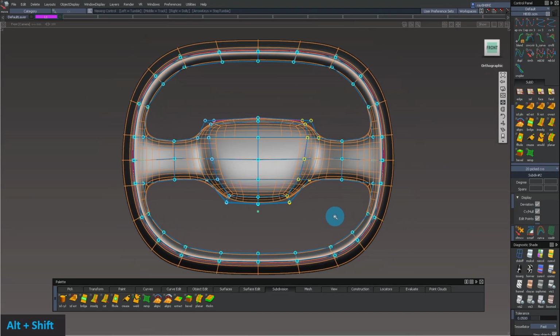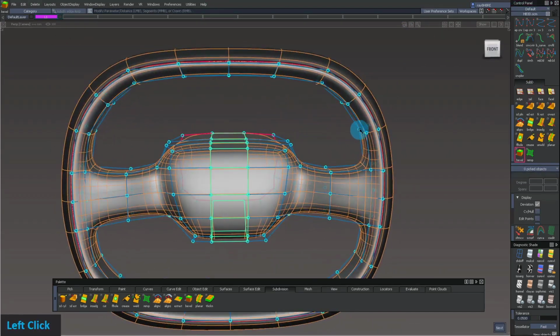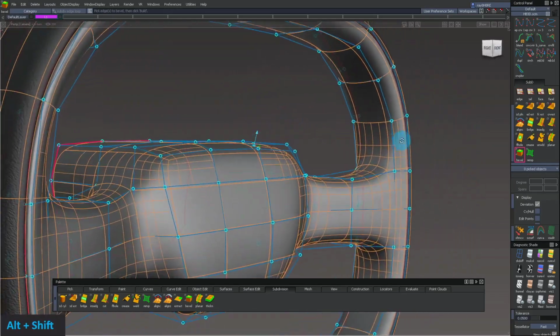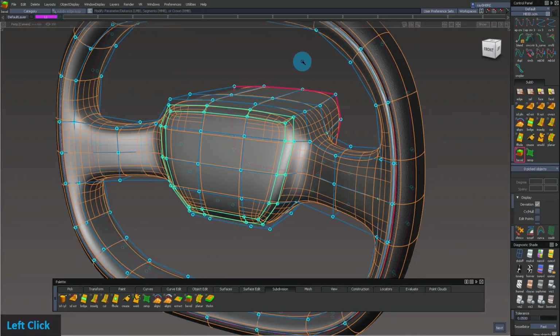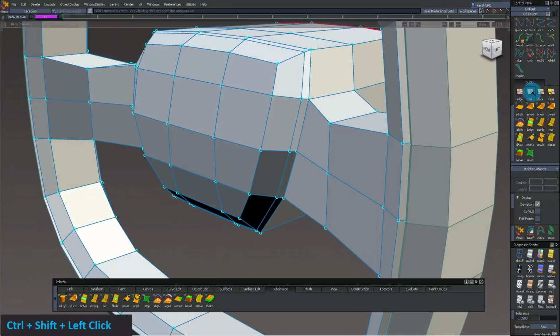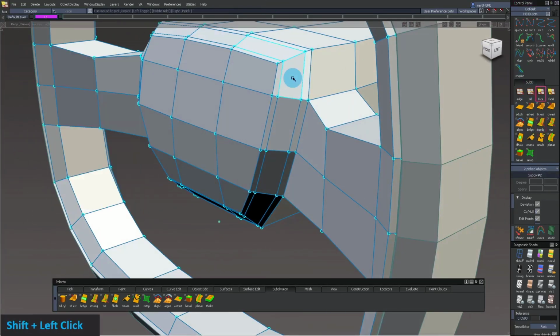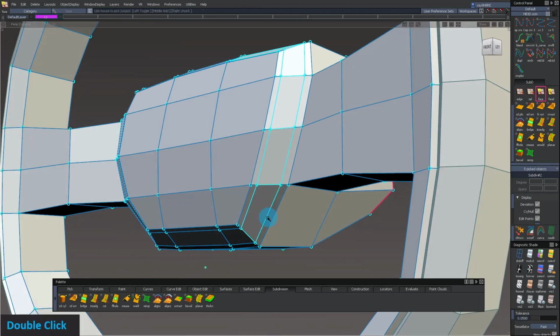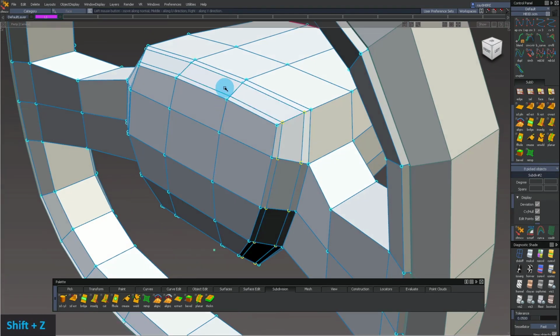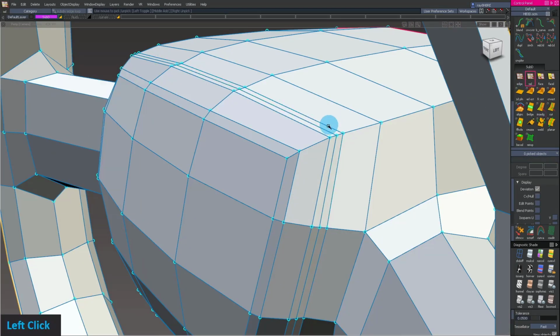From here, it's looking a lot more like my final model, and I'm just adding more and more CVs. I hope you guys notice that I'm slowly building everything up, and it's slowly getting more form and shape. This is why the end result becomes really clean, because I do the bigger parts first, and then add more details to the curvature of the form, but obviously this is more my own way of modeling. For that metal frame around the horn, I did the same thing I did with the outer steering wheel, where I beveled it, inserted a loop, and then unwelded them.